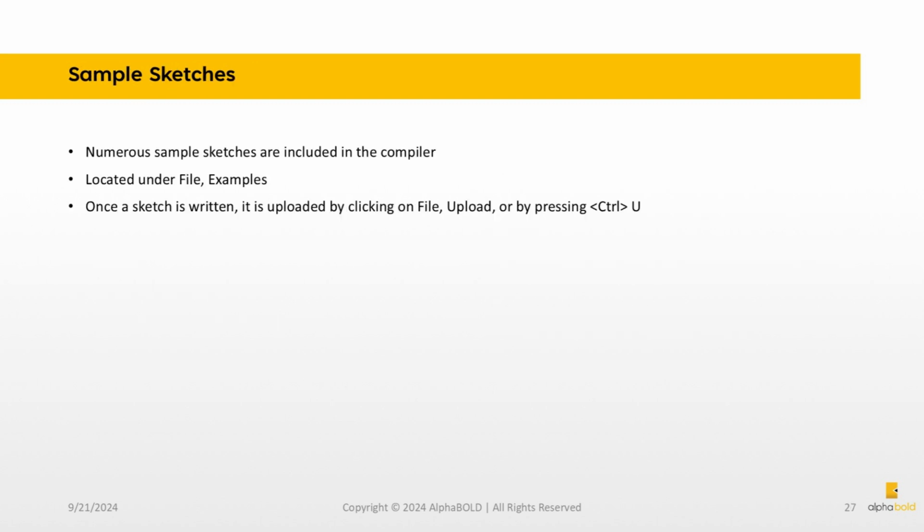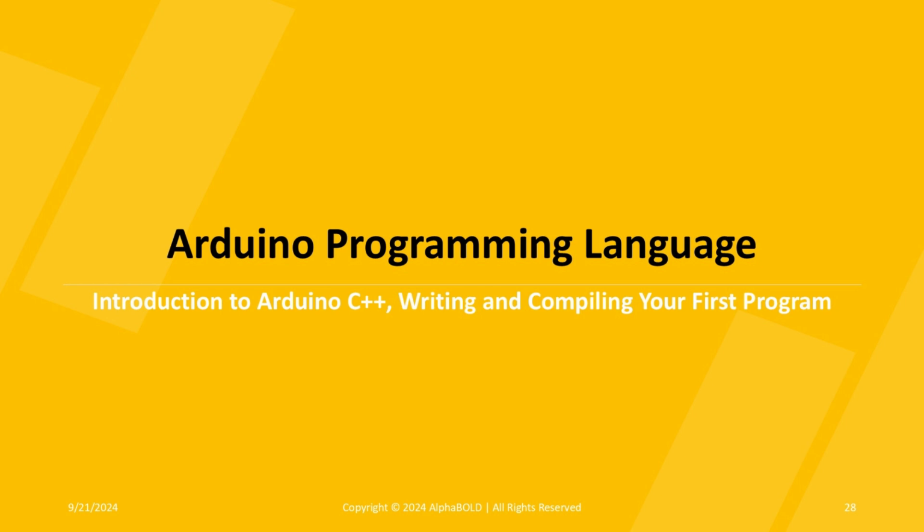Numerous sample sketches are included in the compiler. Located under File, Examples. Once a sketch is written, it is uploaded by clicking on File, Upload, or by pressing Ctrl-U. Arduino Programming Language.